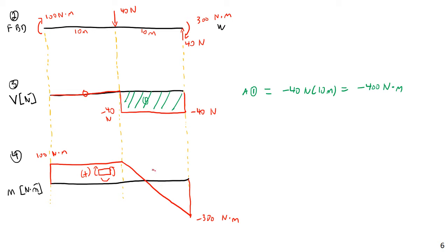And we're going to have an inflection point. We have an inflection point where the beam will go from concave up to concave down. And here, the beam will be bending downward in nice, sad negative bending. Or just negative bending if you prefer. Negative bending like that. And that will be our final shear and moment diagram.